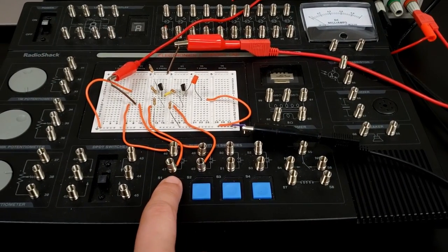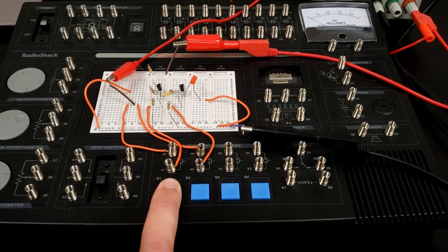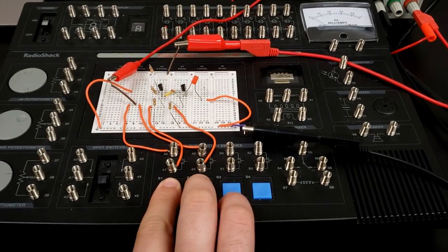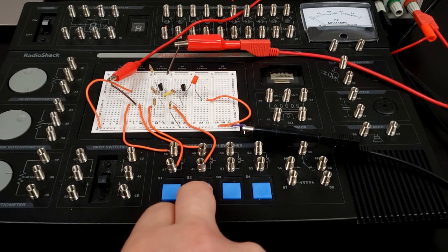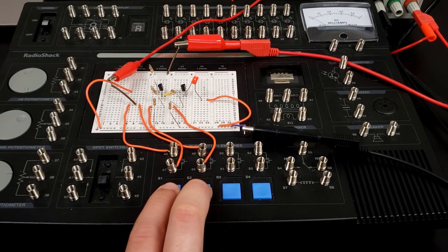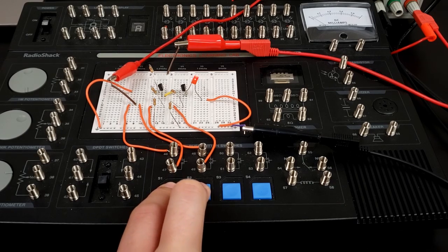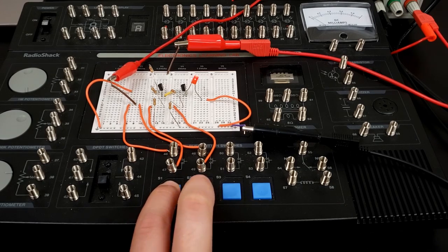Now if we do 1, 0, and press that first switch, you can see that, again, we have no output for our LED. And if we press S2, corresponding to Q2, then again, we have no output. And only when we press both of our switches at the same time do we get an output. Okay, so this first transistor circuit would be an AND gate, as we talked about in the introduction.